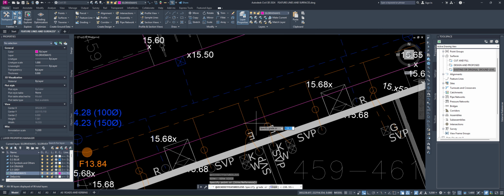So if you want to be, let's say, at 20 mil per meter, we're going to type 20 mil per meter. Let's press enter. And what's going to happen now is it's going to apply an extra 20 mil per meter from that point to that point, which in our case looks like 10 meters here. Then 20 by 10 is going to be an extra 200 mil nearly.